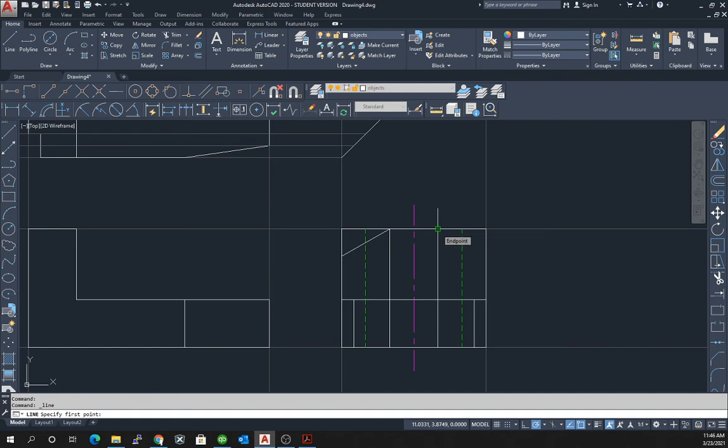And over here, I'm going to show it to you the other way. So over here, we start a line, and I'm going to make it an arbitrary length. So I'm going to make it a length of 2, and then an angle of minus 30. And when I do it this way, I have to then take the line, and then I select the line, and then I choose lengthen to bring it back to the intersection.